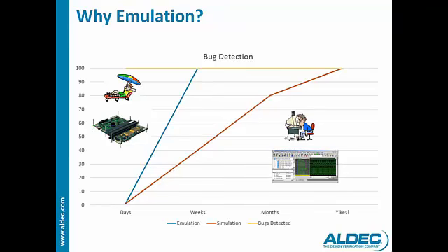Certain applications, such as audio and video, have to be verified in real time with human interaction. Emulation connected to actual hardware can run real diagnostic code, operating systems and applications. And with real chips, internal probing isn't possible once the chip has been fabbed and placed in a system, but it can be possible using emulation.